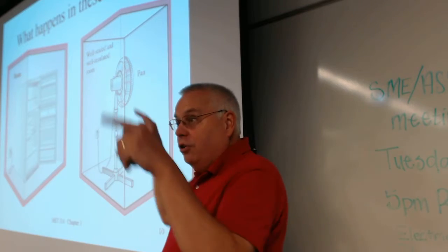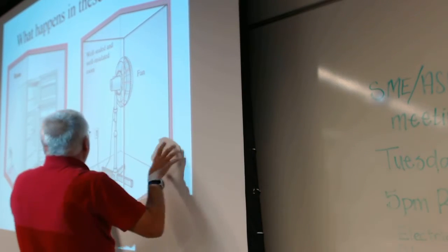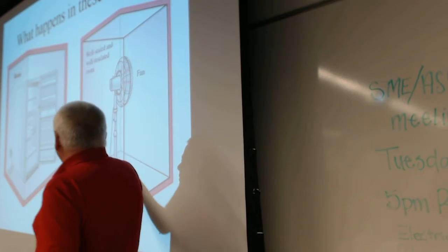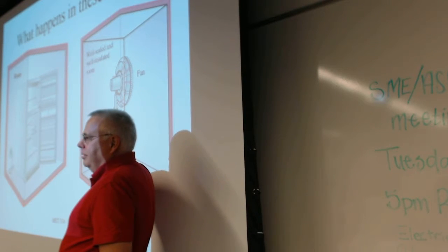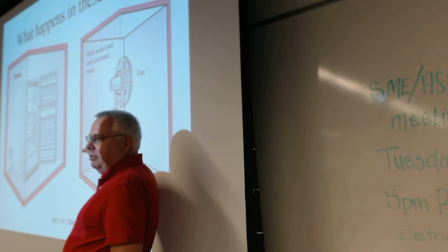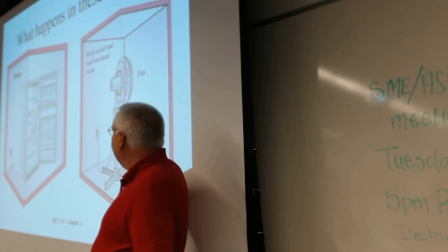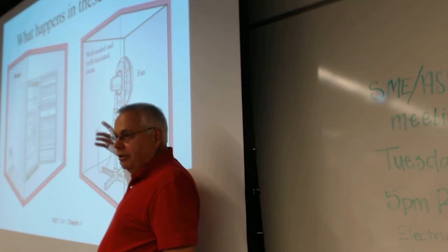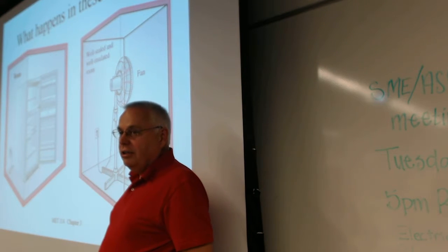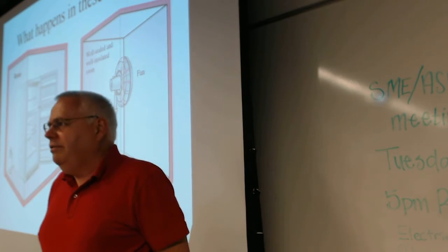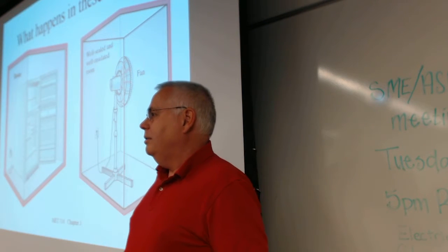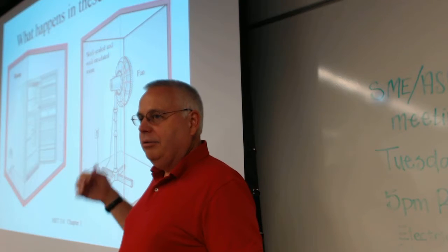So that's first law. Draw a box around it. It's insulated, no heat going in or out. We've got power coming in. 100 watts times 10 hours, you can figure out how many kilojoules that is. And then if you know the mass of air in the room and maybe the mass of whatever's heating up, you could come up with how much temperature it's going to rise. It might be insignificant, but it's going to be a net rise. So that's an example of our first law.